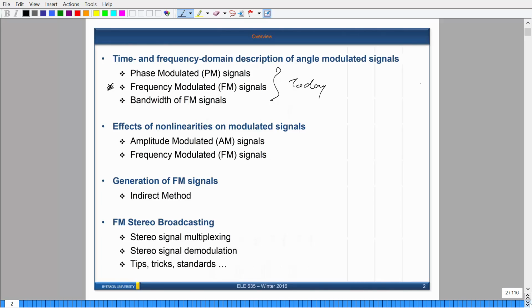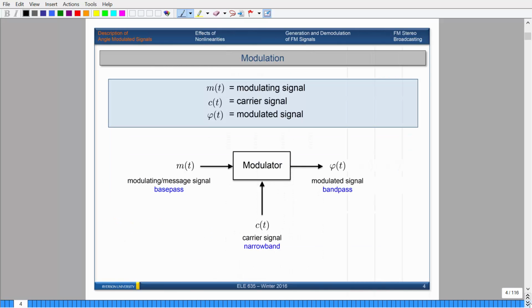Okay? Okay. So just a quick review of modulation. We've already seen this before, right? Modulation is concerned with varying either the amplitude or the frequency of your carrier wave. Okay, so amplitude modulation is concerned with changing the height of your carrier, depending on the height of the actual message contents themselves.